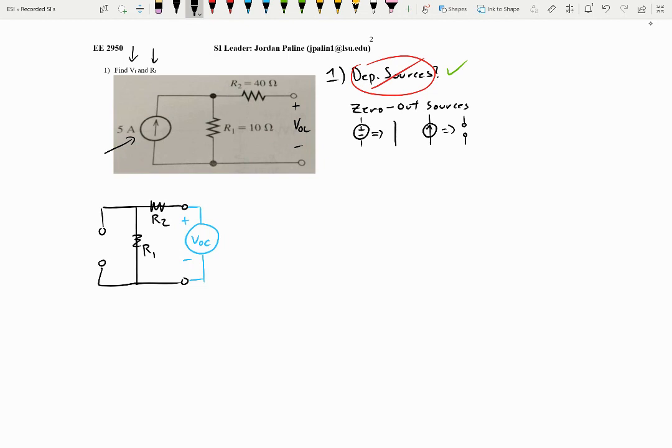Okay. So if we're treating this like a battery, we're saying, okay, so some current's going to leave here and just head into this circuit. If we have a current leaving here, travel up through this way, go through this resistor, but then it'll hit this point right here. So it sees that it has two options. You can either go this way, where there's an open wire, or it can go this way, where there's a resistance.